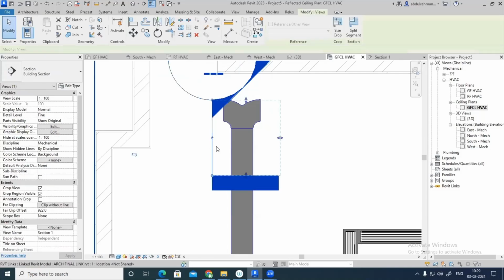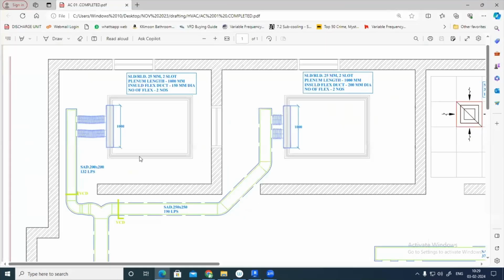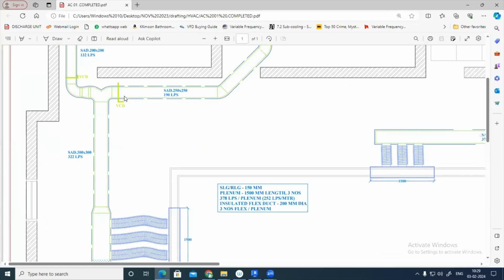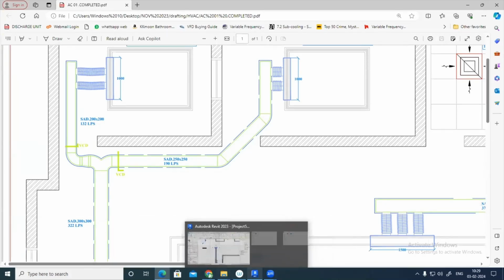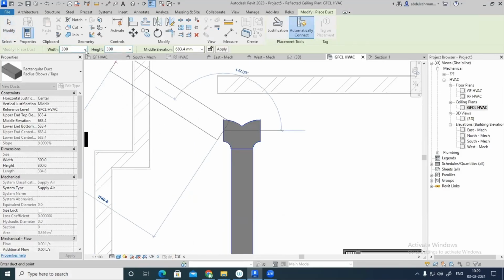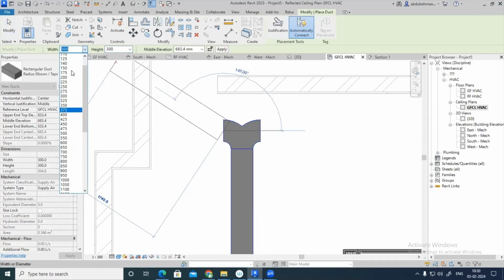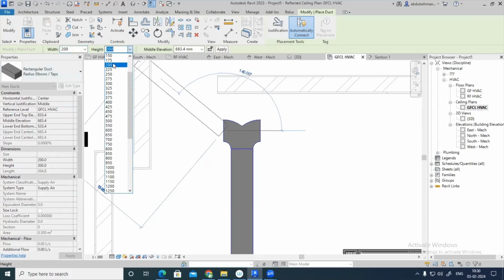Okay. So this family I have created. Now you can see slightly you have to take it right side. Right side anyhow from 300 to 250. One more fittings will come that we can show by a line here, but I have it. Left side it is 200, 200. This is 250, 250. So 200, 200, 250, 250. Selected. The dimension should be 200, 200.